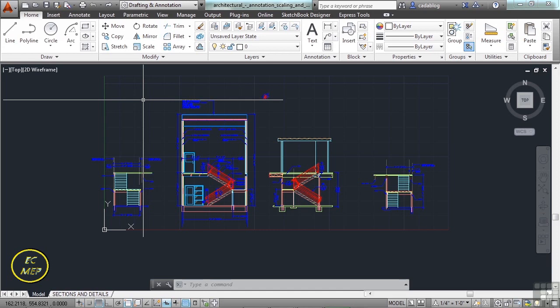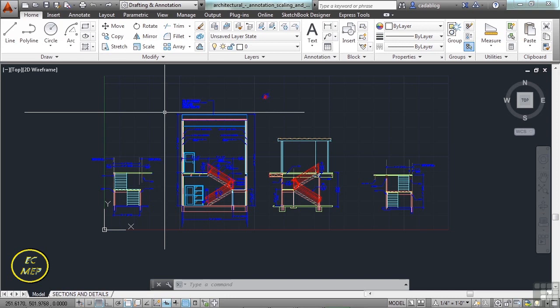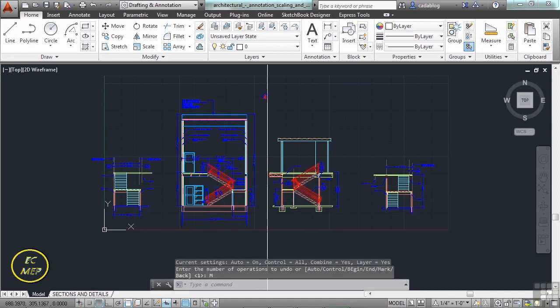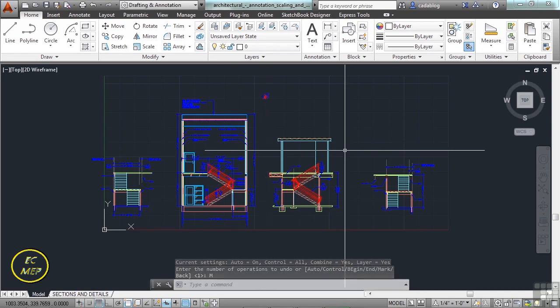You can't undo those. You can mark places in time as references for the undo command, but that's getting rather complicated right now, and to be honest, in almost 20 years that I've been doing this, I have never had a need to do that. So let's say, okay, I'm going to work on a concept design. I want to mark this place in time. So you would type in the word undo, and you would click mark. Now AutoCAD knows this point, and everything I do from here on is set. So I can do some things.